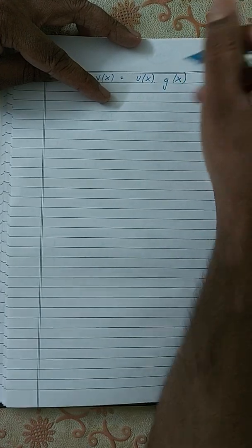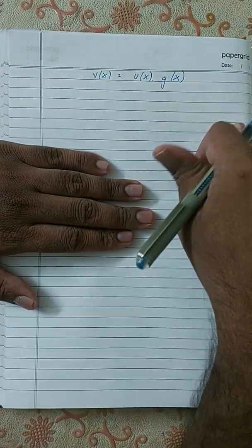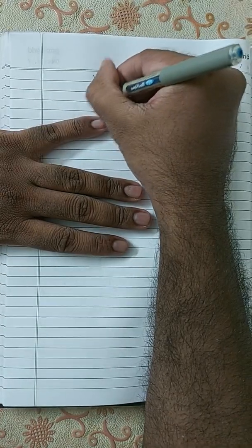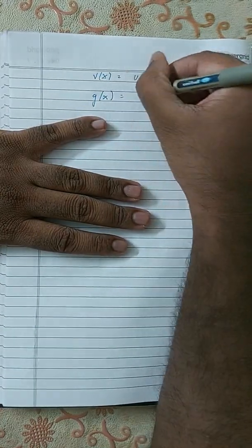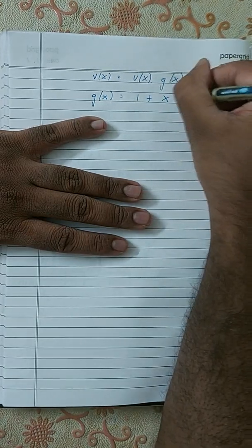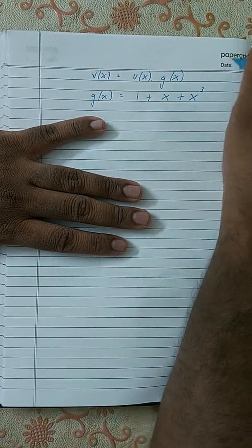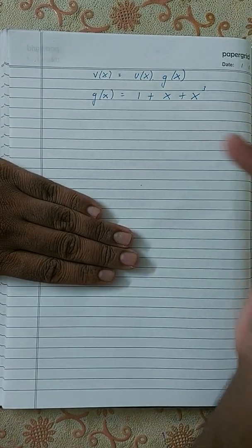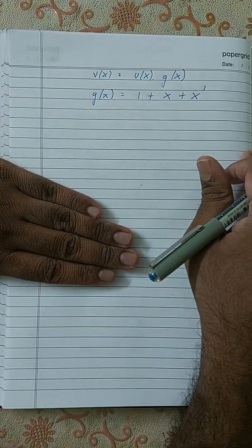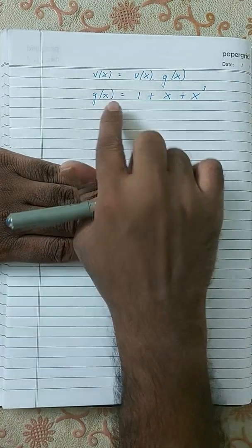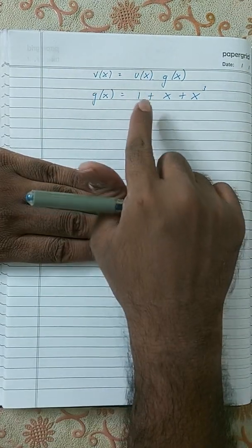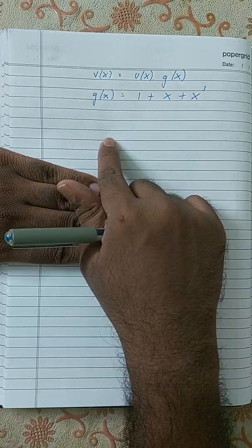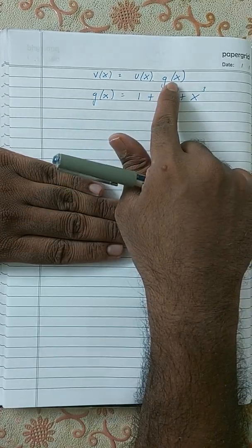In the previous video, for the non-systematic cyclic code, when we discussed how to create the generator matrix or the generator polynomial, I told you that the generator polynomial I chose for a 7-4 cyclic code was g of x equal to 1 plus x cube. So this is 1 plus x cube.